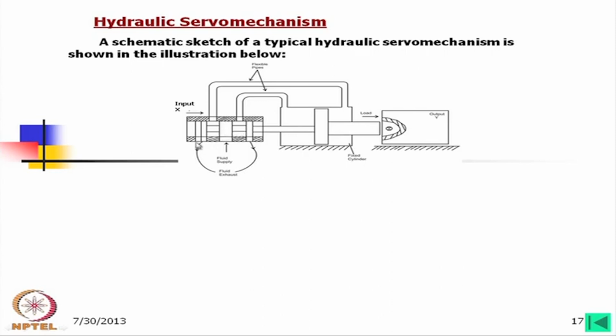When we give an input, the load moves, but looking into position and motion, the valve body, the outside body, also moves, and by that closes the motion of the load. And again with the presence of input, the spool will move further and the load will be moved.